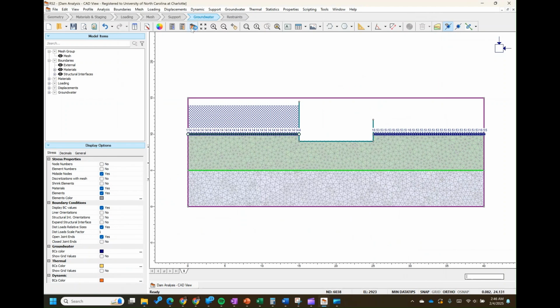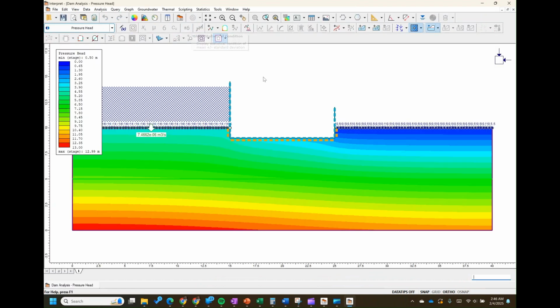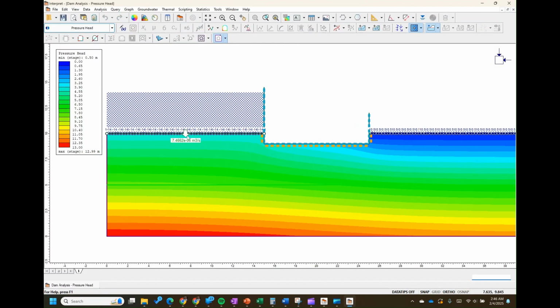After computing, we can check our results using interpret. So this is showing us the seepage flow. This is the influx into the domain. So for us to select a good domain, we can do 2 times the depth. This current one is 1.5, which is 15 here. If we do 2 times, that will be 20 to the left and to the right.